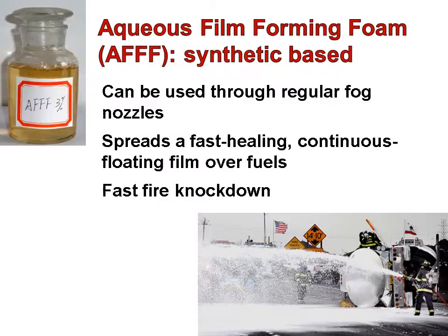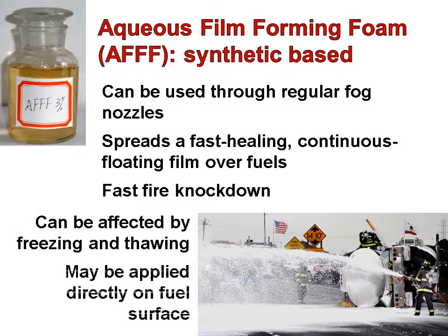May be applied directly on the fuel surface. Must cover the entire fuel surface. And may be used with subsurface injection. The foam blanket continues to drain water, releasing more film, allowing AFFF to heal over areas where the blanket has been disturbed.